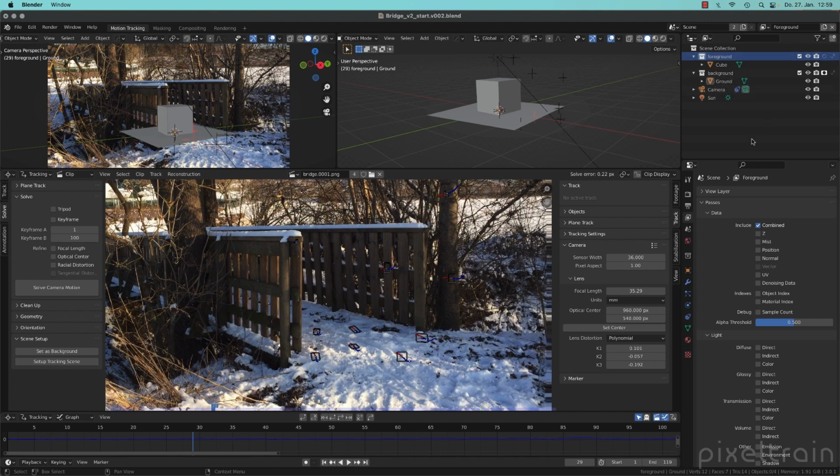The interesting thing is that if you have these view layers, they are rendered in a sequence. Blender will render now 2 times. One rendering is for the foreground, which looks now exactly like this here, only rendered. And if you go now here to background, you will then see that the output here will switch. Let's go back here to see that. So if you are on foreground here, you only see the cube.